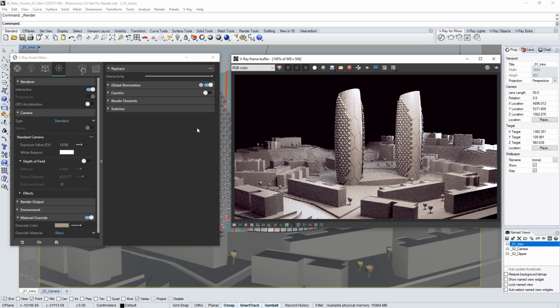Using the interactive rendering, you can take advantage of your CPU or GPU power. By default, it's based on CPU utilization. With one or two processor units, VRay can render with more than 64 threads, and if you have a decent graphic card or more than one, you can use it to render with it. Activating the GPU from here, the rendering will be GPU accelerated.